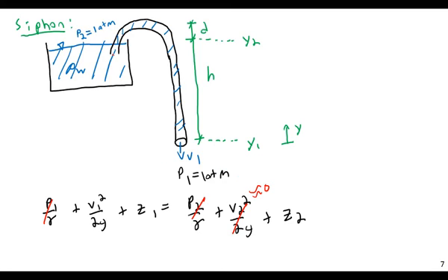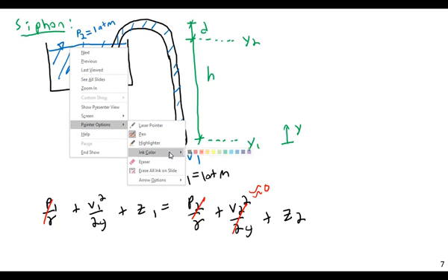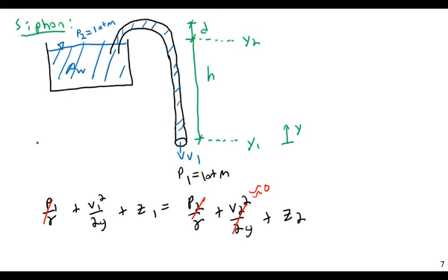Now, right at the edge of the boundary, right at the cross section of the pipe or the tube, the velocity won't be 0. But I'm comparing this point to this point, right at the surface. When you immerse a pipe in a fluid, or you're looking at a fluid entrance, there is a velocity field where a pipe meets a tank. Close to the pipe you have the max velocity, further away you have smaller velocities, and over here you essentially have 0 velocity. That's how fluids actually flow from tanks into pipes. You start with 0 velocity around this boundary, and then there's a slow transition region as you go towards the pipe.